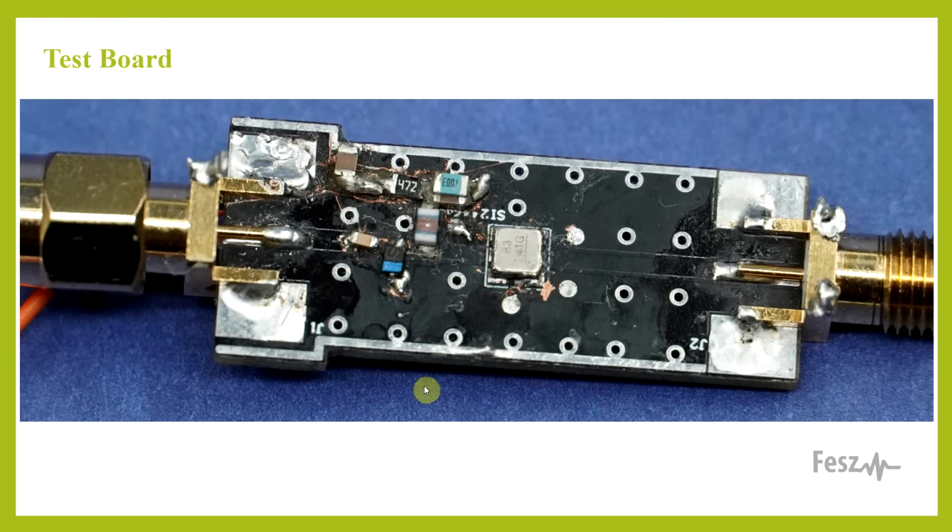So, to test out the pin diode switch, I wanted to see how it can be used to attenuate the incoming signal, to prevent the overdriving of the filter and the radio. First, I took the filter board that I had and modified it a bit to add in the diode, as well as the other necessary components. So the series inductor, a local decoupling capacitor, and then a series resistor through which the whole circuit is supplied. So the whole thing came out looking quite compact.